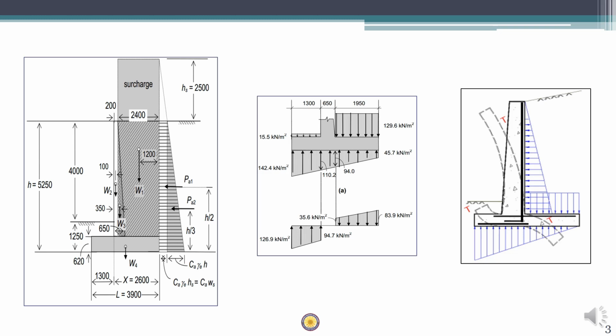So since the toe slab bends upward, you can see that the tension side is on the bottom side and hence the reinforcement is given in the bottom face. On the other side, the heel slab, the net downward force is more, hence the heel slab bends downward. So you can see that the tension side is on the top side and hence the tension reinforcement is provided on the top in heel slab.